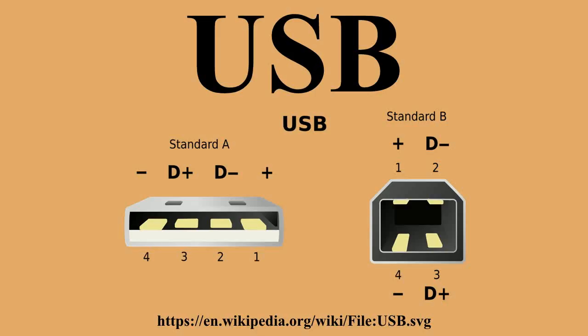The device address and endpoint of a pipe is addressable with a tuple specified in a token packet that the host sends when it wants to start a data transfer session. If the direction of the data transfer is from the host to the endpoint, an out packet having the desired device address and endpoint number is sent by the host. If the direction of the data transfer is from the device to the host, the host sends an in packet instead.